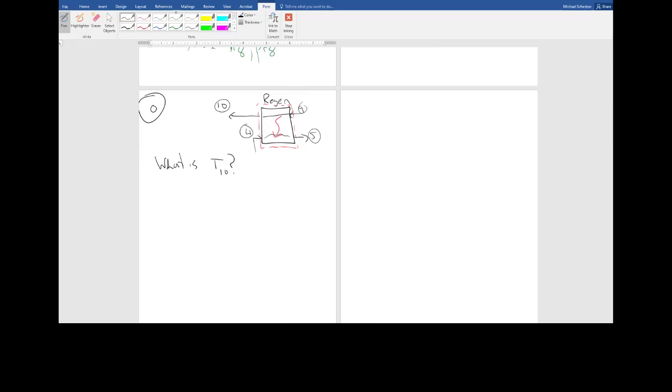Do the first law. When you don't know what to do, try the first law. On the regenerator in this case. Because regenerator efficiency won't help us. Because the regenerator efficiency only tells us what's going on between 4 and 5.